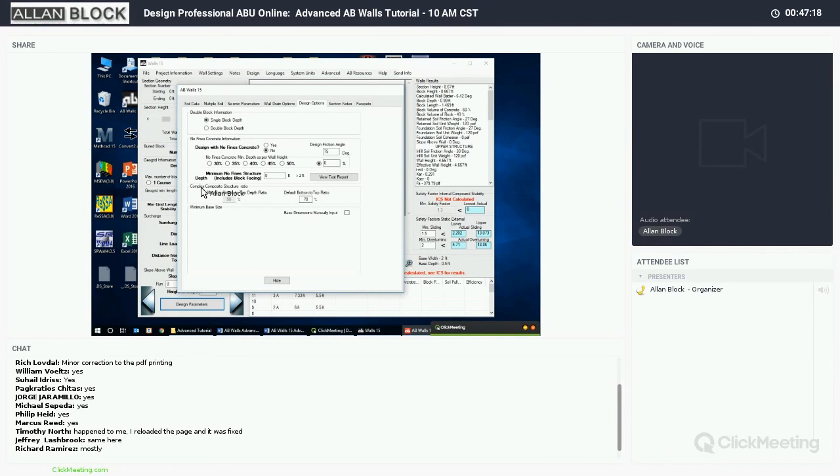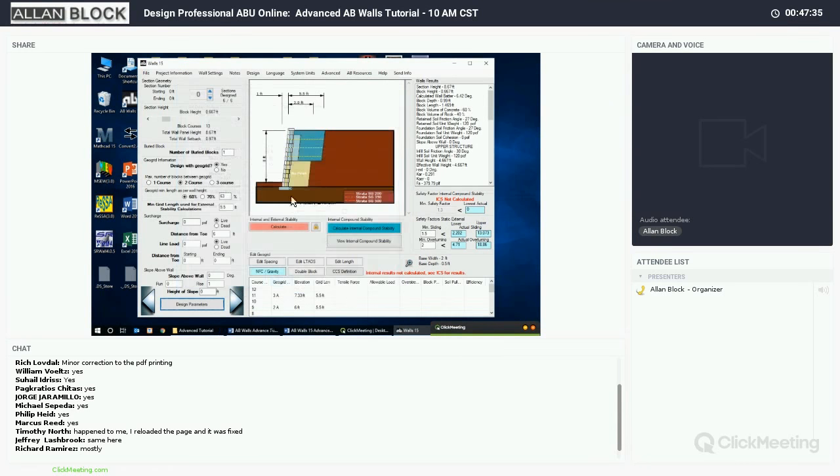but notice this tab right here, or this section, complex composite structure ratio. Minimum bottom needs to be at least 50%. Okay? Top default ratio is 70%. So you have some control over this. You can change the ratio, but notice that 50% rule is kind of grayed out. That's part of that. So I can't go less than 50% without making some modifications through some hand calculations.